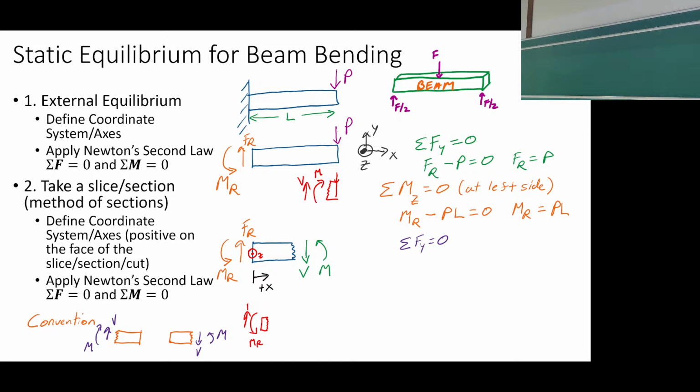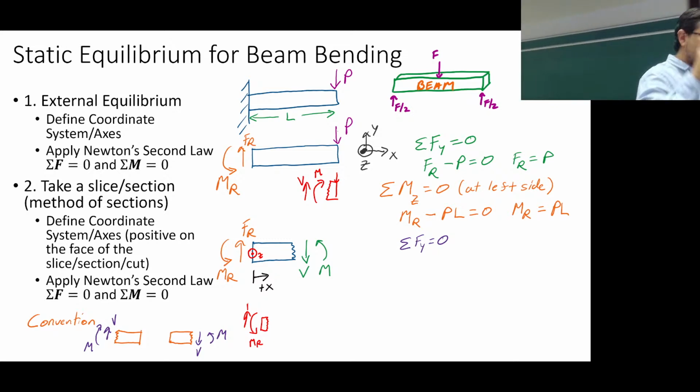Notice once again, though, the V's describe the same behavior. Like I can take a bar and slice it and leave the right open, right? And when I do that, I have a positive V going down. Or I can slice it and leave the left open, and then I have a positive V going up. Wherever the slice was.